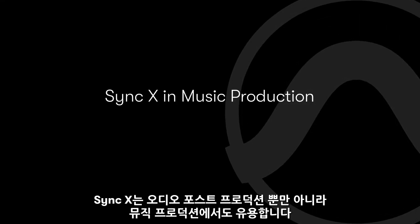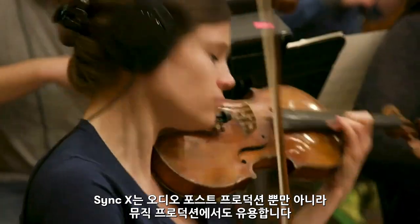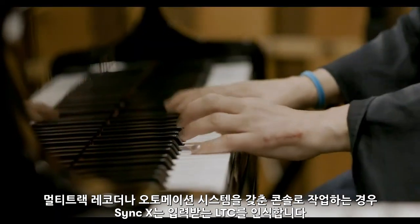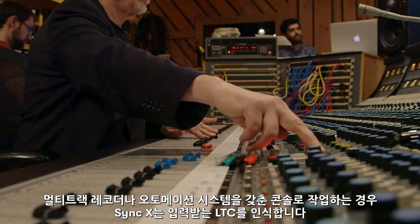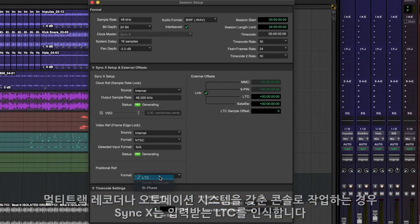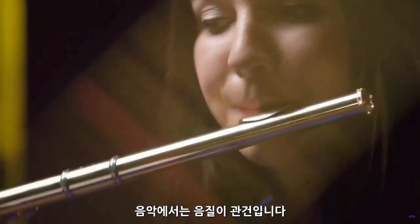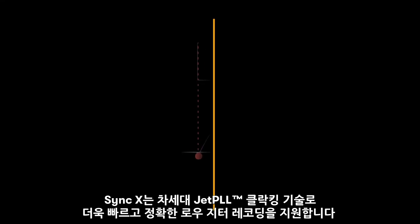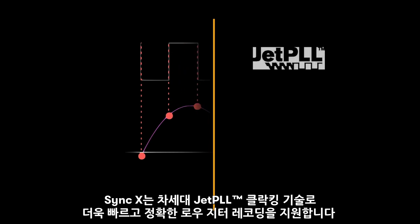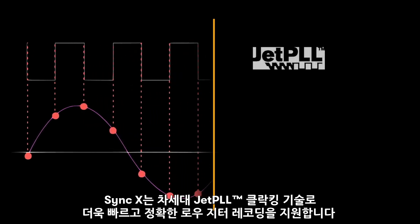Sync X is an essential component in audio post, but of course synchronization is also required in many music production scenarios. If you're working with a traditional multi-track recorder or a console with its own automation system, Sync X interprets incoming LTC. In fact, it can even track playback speed from the timecode stream if there's no separate clock. In music, the most important requirement is audio quality. Sync X has the next generation JET PLL clocking technology, providing a faster and more accurate lock with low jitter for the best quality capture.